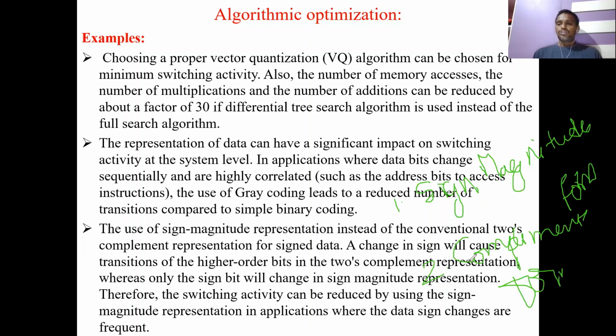Okay, so these numbers, the signed magnitude numbers, are signed numbers. Signed means there is a sign, unsigned means there is no sign represented before the binary representation. If a number is signed, there will be a plus or minus. Plus is always the general representation itself, but if the negative sign is there, we call that a signed number. Signed binary numbers can be represented in two forms: one is signed magnitude form and the other is complement form, that is 2's complement form.